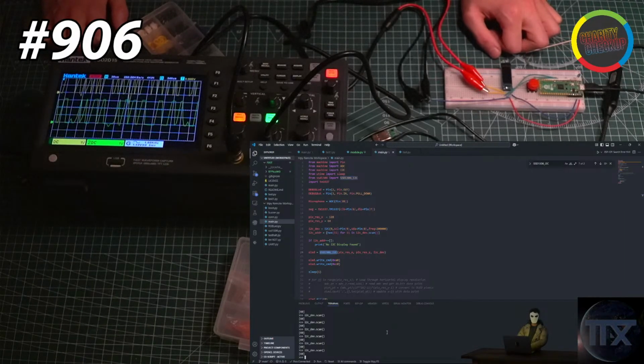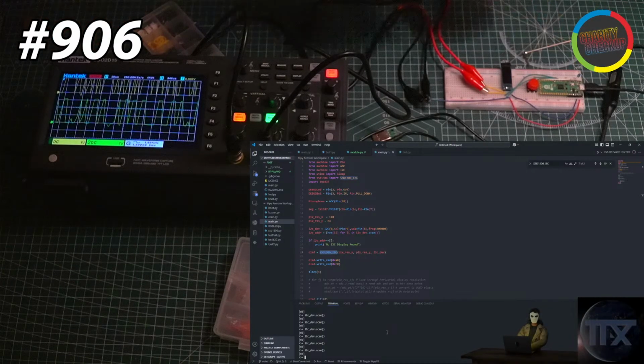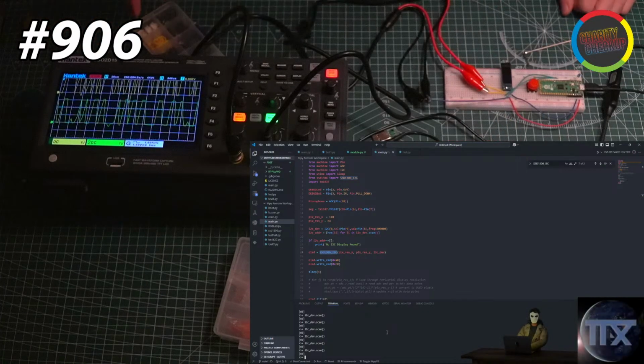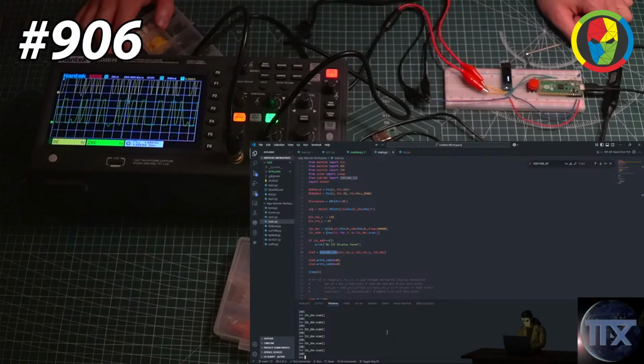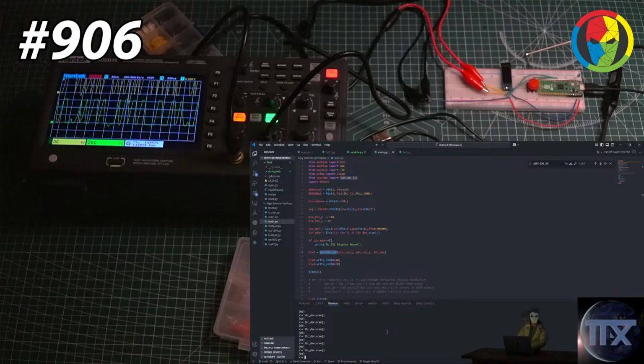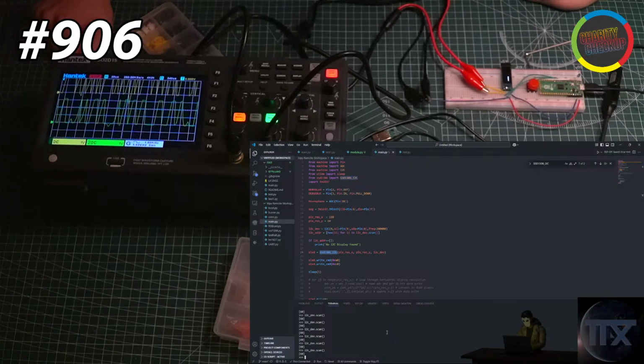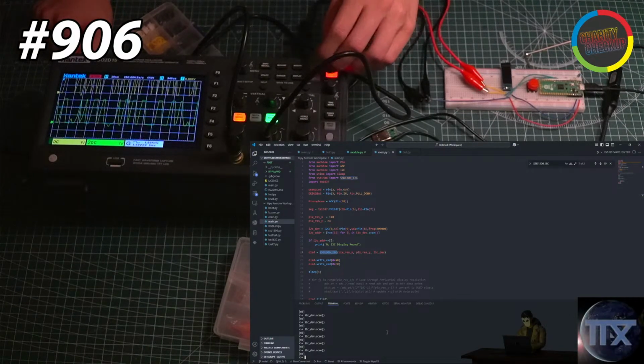I would love to connect the oscilloscope in between the data of the LED pins when I actually have the band, to compare with the coupling capacitors versus without. And you should be able to, because you have gigasamples per second, and I think you have a 150 megahertz oscilloscope. You should be able to see a lot as long as it's not a higher frequency than that. So that's your only limitation.